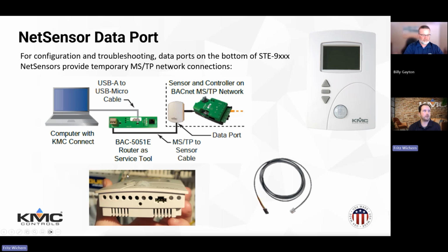You've got a little diagram here of the ability to connect it up from the data port to a router as a service tool, or as an option, you could use a USB to RS-485 adapter as well to be able to go from your laptop with Connect and scan that trunk. So some options there. And if you don't know what I'm talking about, it's that little data port here in the bottom picture, the little 4-pin plug there.